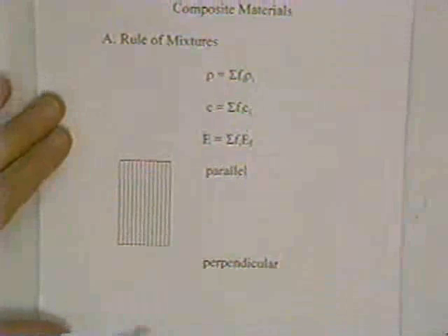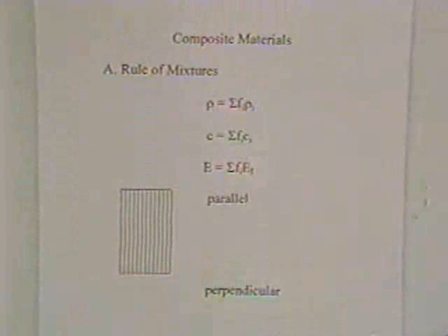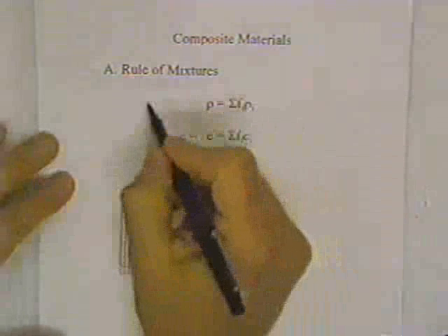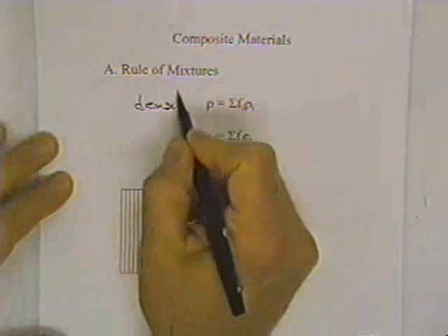The last thing that we're going to talk about will be composite materials. Some examples of composite materials, the kinds of things that might be helpful to you, would be application of the rule of mixtures. This says if two phases or two properties are not mutually dissolvable in one another and are independent, we can describe them by a sum of the individual properties. For example, the density.